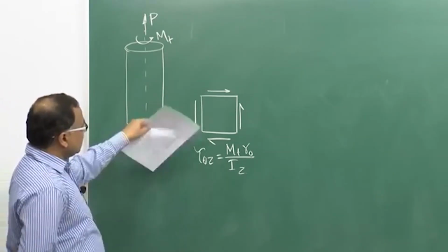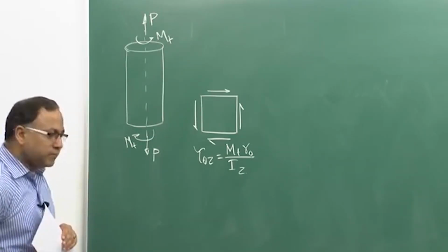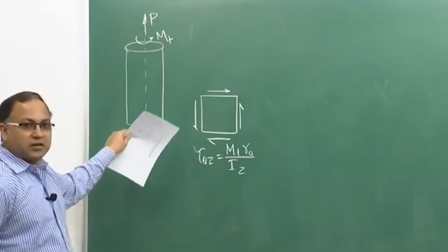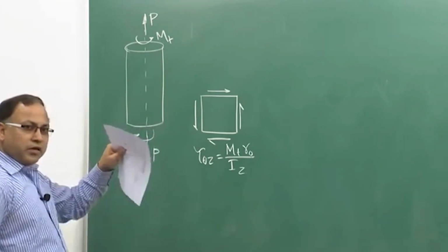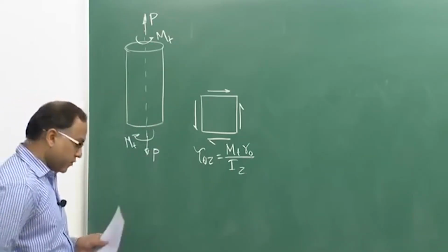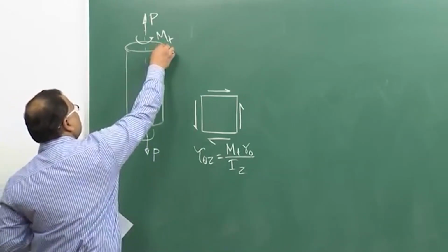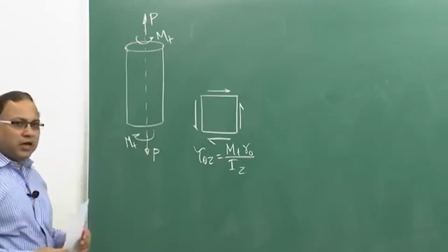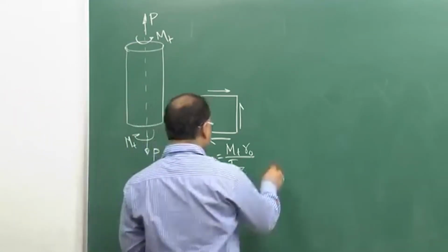So, this is the stress getting developed due to the twisting moment, okay, only pure shear, right, there is no other stress available there. Already if you recall from the torsion chapter, only shear stress will be developed, okay, and we are talking about the maximum shear stress. That means we are just dealing with the peripheral point. So, maximum shear stress will be developed at the periphery.